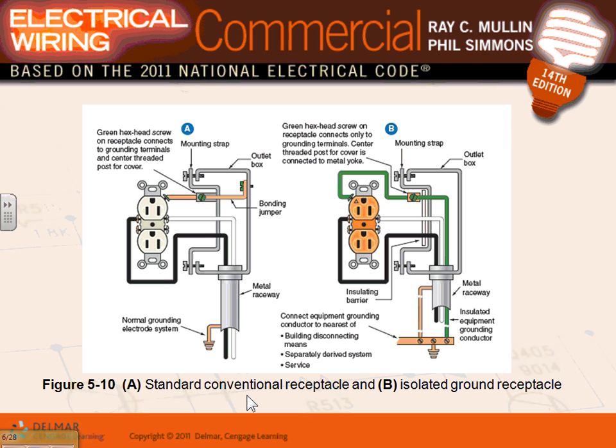So I can't use an isolated ground conductor with this one, for example. It completely defeats the purpose of having an isolated ground receptacle, because the ears right in here, as well as the grounding slot, represented by this little button, are all tied together, metallically tied together.